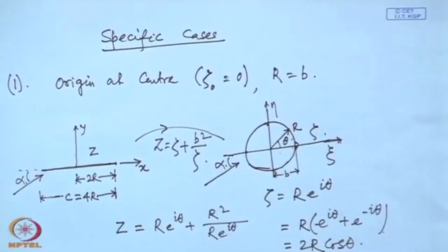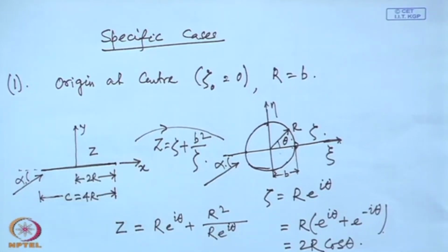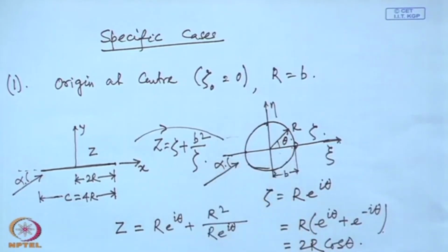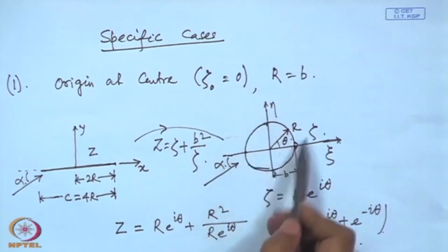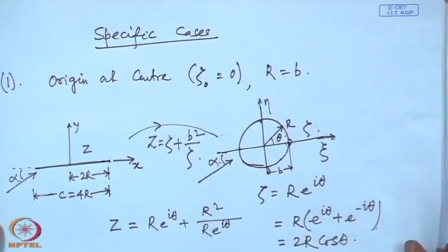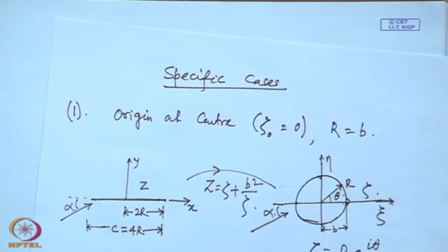All other flow properties, that is the flow velocity on the transformed plane, that is on the z plane, that is flow velocity over the flat plate airfoil, can again be obtained using those formula that we have already developed. Velocity on the circle divided by that dz d zeta. Pressure can be obtained then using the Bernoulli's equation. Lift, of course, we have already derived that A by C. How much is the lift force?